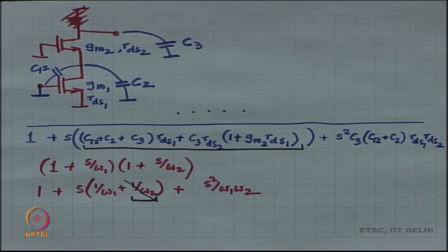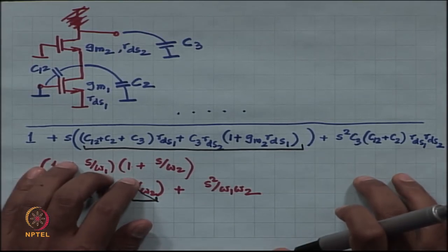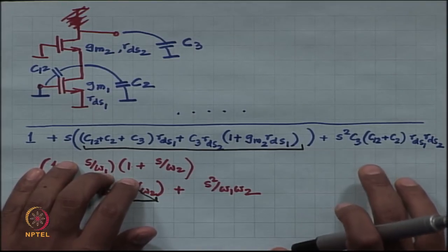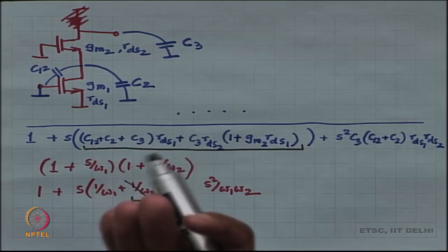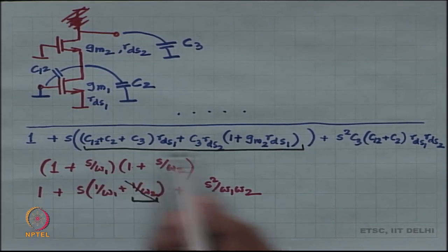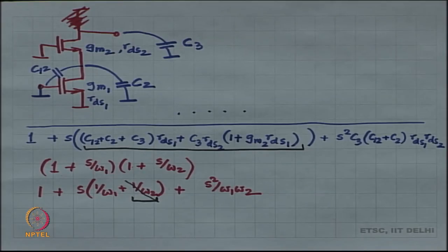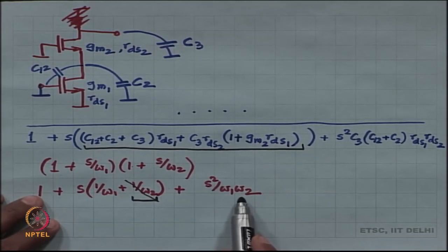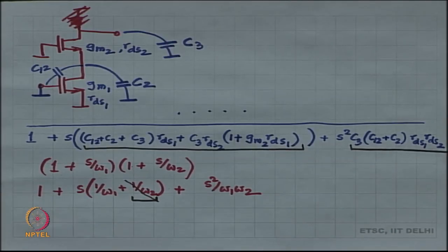Done, right. So, we do not really know how to factorize this analytically, but we know how to arrive at the two poles by inspection looking at the quadratic equation, right. So, my 1 by omega 1 is nothing but what I have got, and if I know 1 by omega 1, then 1 by omega 2 is a no brainer, because the product of omega 1 and omega 2 is 1 by of the third coefficient. Okay. So, omega 2 is also a no brainer, and then you have to set omega 2 by omega 1 equal to whatever that gigantic number you had.